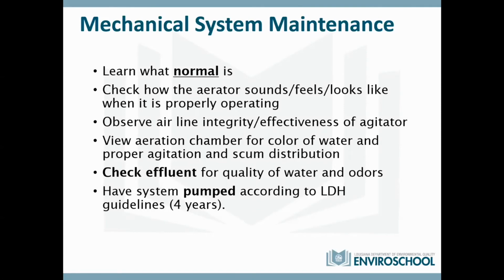There's always a line from these blowers to the actual aeration tank itself. Check these lines. Sometimes they can get dry rotted. Sometimes people accidentally cut them when they're out mowing or weed eating. Sometimes they get knocked loose or they just fall apart. So be sure that you have a seal between the blower and the system itself, no holes in it. Otherwise, that system is not doing what it's designed to do. It needs that specific air coming from that specific blower through that line, the way it's designed, to work properly.